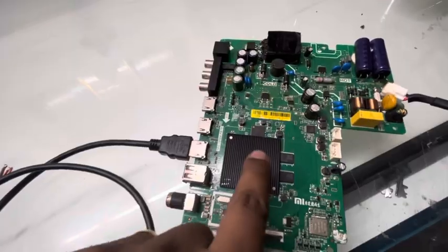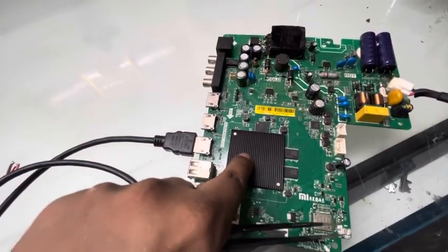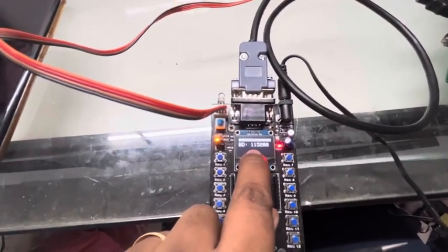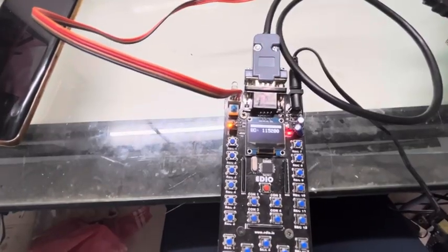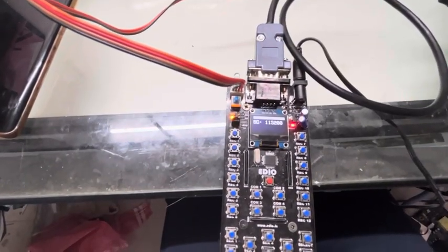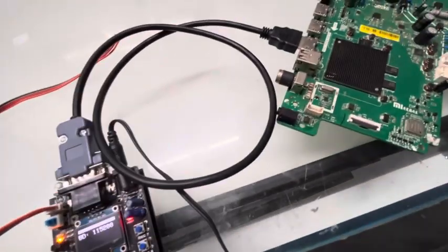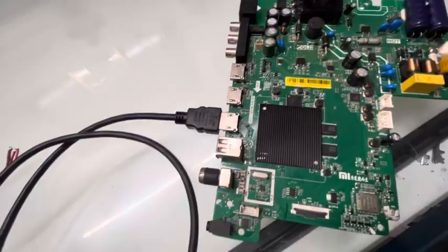So you have to connect the correct UART port, then only you will get proper data. Then this motherboard's baud rate is 115200. You have to know the correct baud rate, because you have to enter it here. Most motherboards, 90%, are 115200, so no need to change anything in this process. Then you must know the processor of this motherboard.